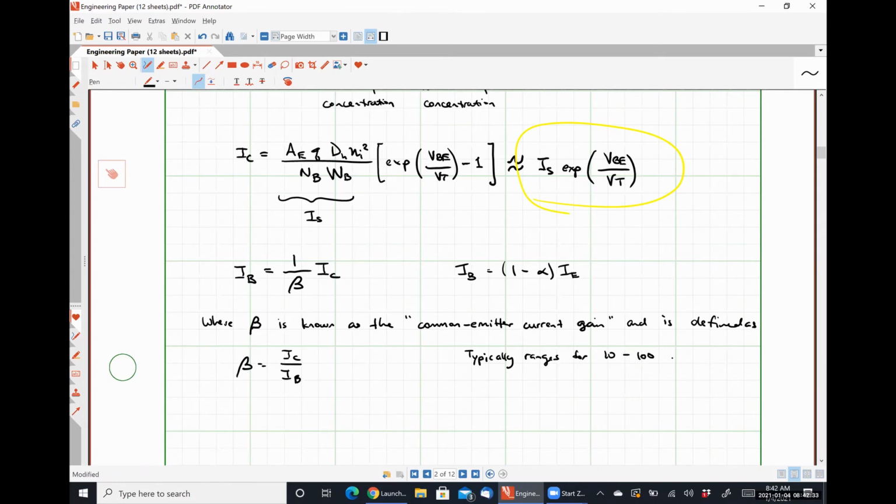What you get is what's called HFE. This is the exact same thing. This is the common emitter current gain, and the F stands for the forward active region, and the E lets you know that it's the emitter current gain. Okay? So on a data sheet, it doesn't say beta is equal to something. It says HFE is equal to something because the H parameter is what's more commonly used in industry, but it literally represents the exact same thing, the common emitter current gain. Just wanted to make a note of that.